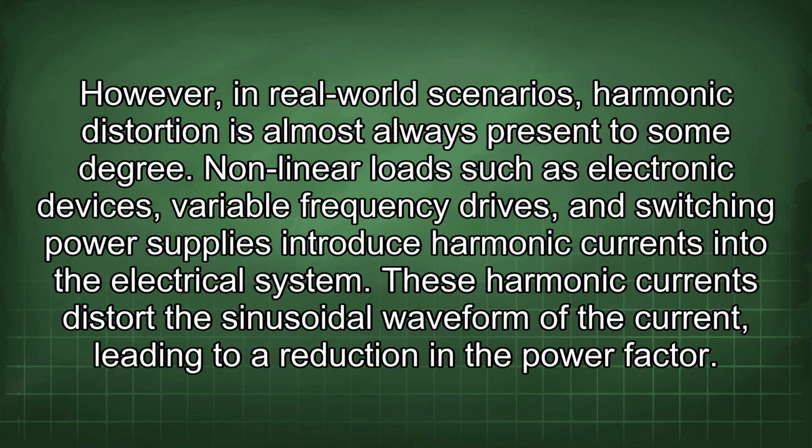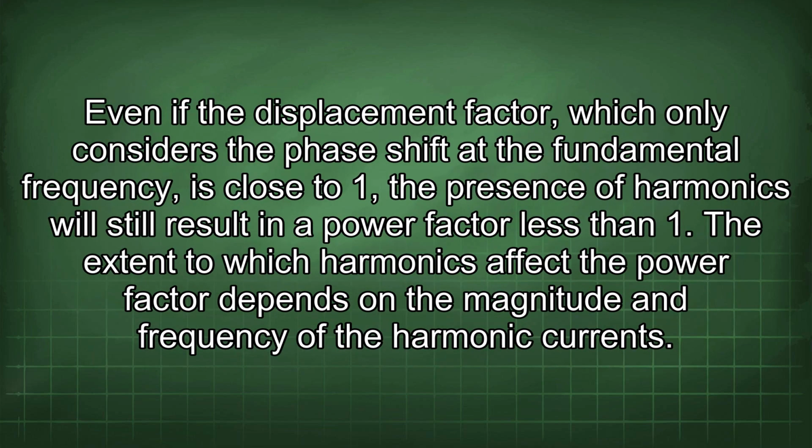However, in real-world scenarios, harmonic distortion is almost always present to some degree. Nonlinear loads such as electronic devices, variable frequency drives, and switching power supplies introduce harmonic currents into the electrical system. These harmonic currents distort the sinusoidal waveform of the current, leading to a reduction in the power factor. Even if the displacement factor, which only considers the phase shift at the fundamental frequency, is close to 1, the presence of harmonics will still result in a power factor less than 1.